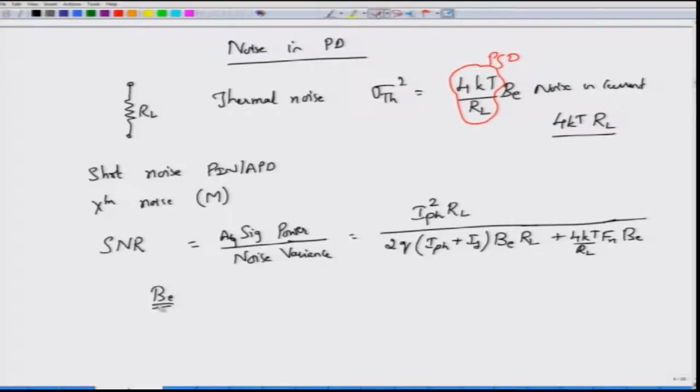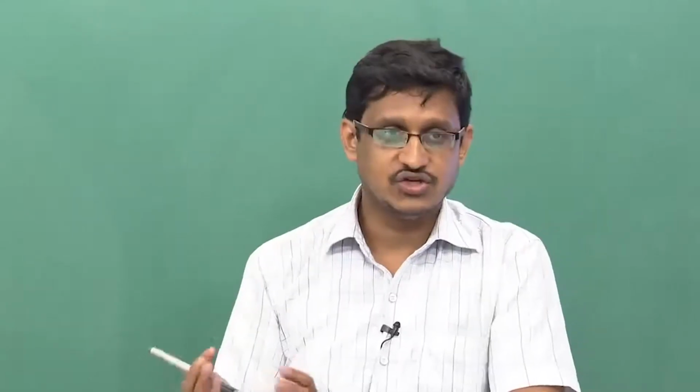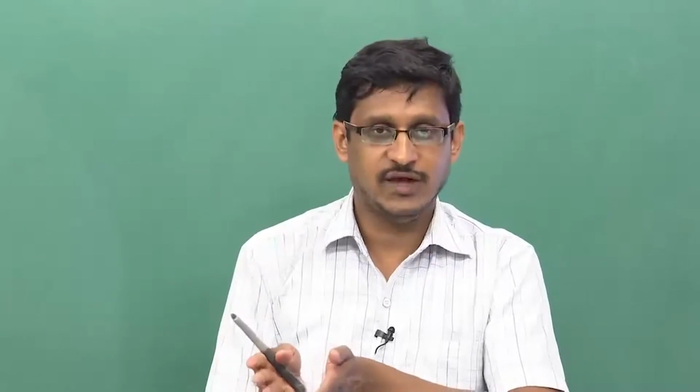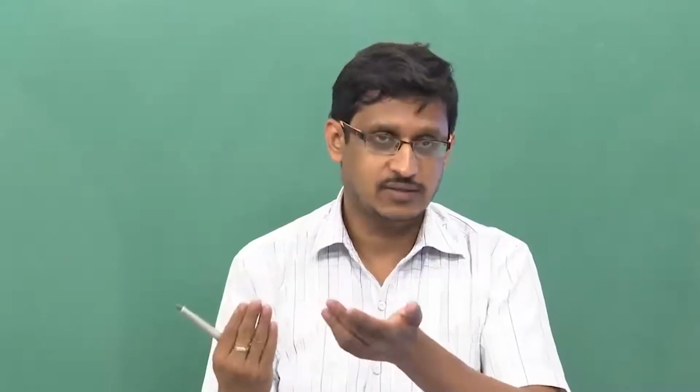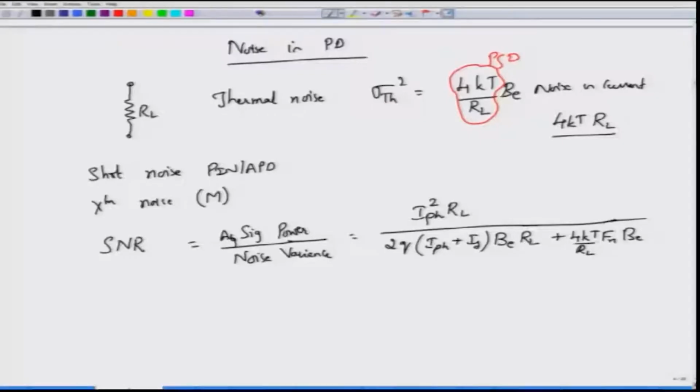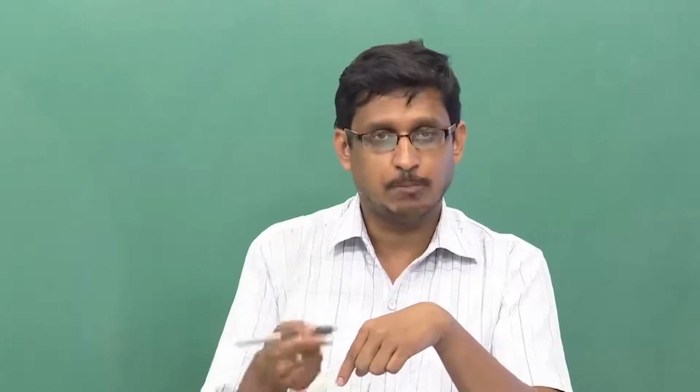Now, signal to noise ratio is given by this expression, but you might be tempted to see if there is any range over which one variance dominates over the other variance, right. So, if I try and make RL very large, then the second term starts to go down because it is inversely proportional to RL, while the first term goes up, right.